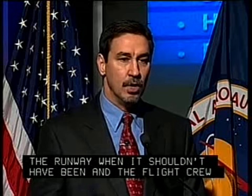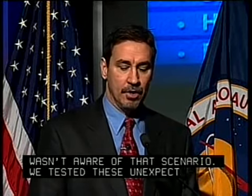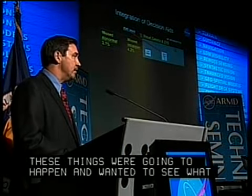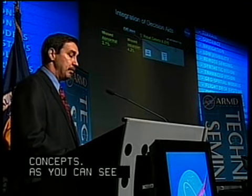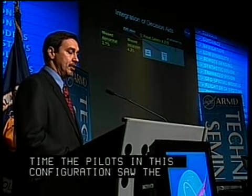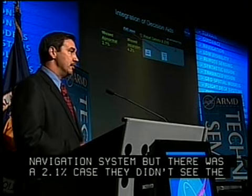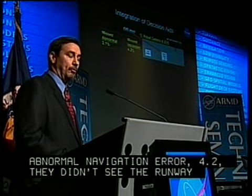So we tested these unexpectedly. We didn't tell the flight crew these things were going to happen, and we wanted to see what their reaction was with these concepts. As you can see here, 98% of the time, the pilots in this configuration saw the abnormal navigation system, but there was a 2.1% case where they didn't see the abnormal navigation error. 4.2, they didn't see the runway incursion. So typically, that's pretty good. They did a fairly good job in terms of picking up those abnormals.